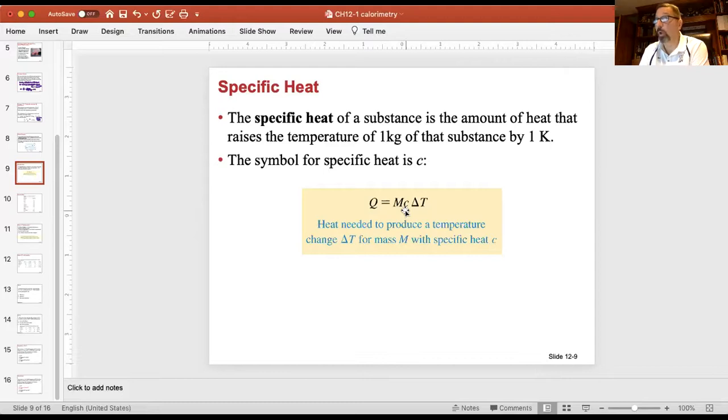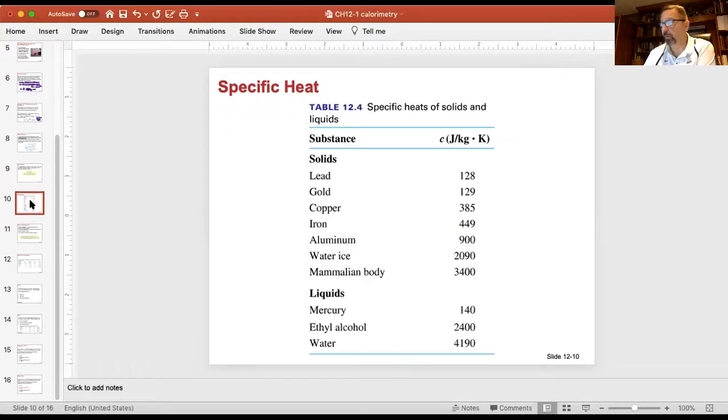Of course, it's not at all 1 degree Fahrenheit or the absolute scale associated with Fahrenheit, the Rankine scale. 1 degree of Kelvin is only equal to 1 degree change in Celsius. In any event, Q is equal to MC delta T. That's good as long as there is no phase change for water, as long as you're not at 0 degrees or at 100 degrees.